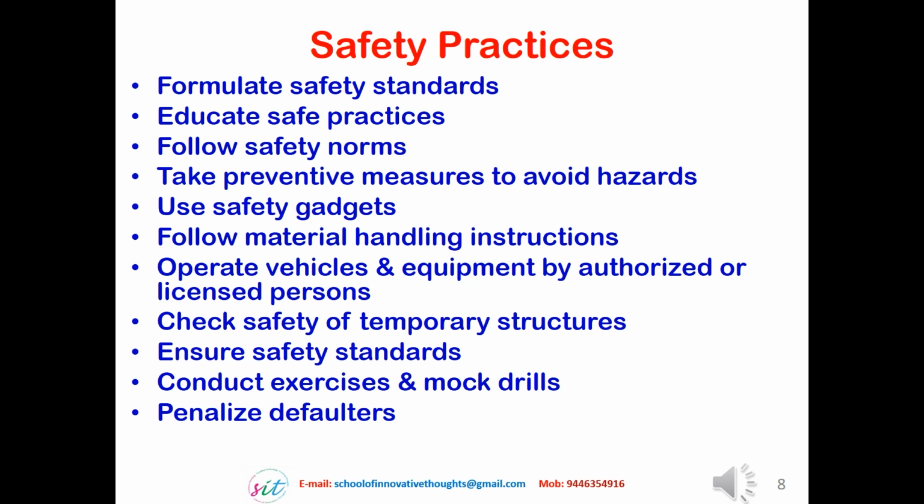The vehicles or equipment should be operated by authorized, trained and licensed persons. The equipment or the vehicle needs to be handled very cautiously, because one of the reasons for accidents at site is the vehicle or the equipment going out of control. Proper training should be given when a new equipment or vehicle is inducted into the organization.